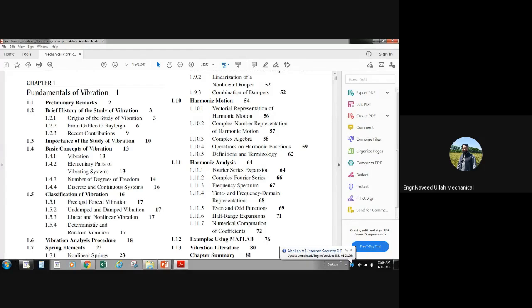So you found out that the natural frequency is equal to the square root of g by l. Initially, that equation of the pendulum is not linear, right? Then we use the assumption that when theta is very, very small, sine theta is approximately equal to theta, and with this assumption you can make that equation a linear equation, okay? But in essence it is not a linear equation, because the sine term is involved over there, okay?